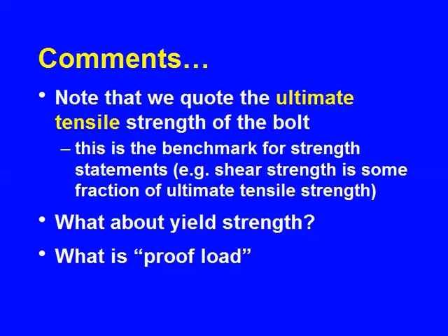Yield strength, I've already introduced the idea that there isn't one for these steels, and there isn't. I'll try to reinforce that as my talk goes on. But you'll also see in the ASTM spec reference to a proof load. Proof load as a generality is the level of load up to which you can load and then unload without more than a certain amount of permanent set. I don't know why it's there. It's probably just put in there to aggravate us. It plays no role in the design of the fasteners, their installation or inspection. So you can take that and set it aside.